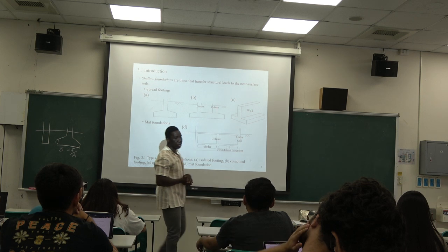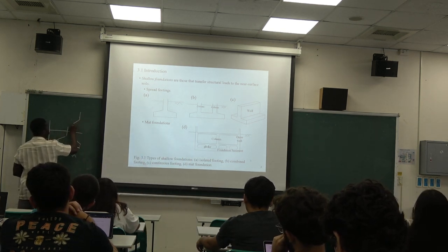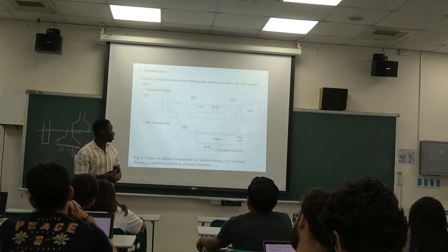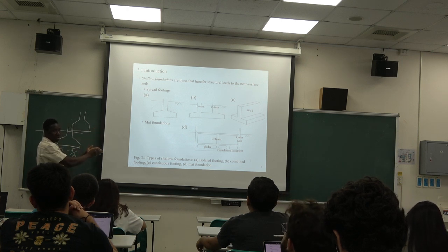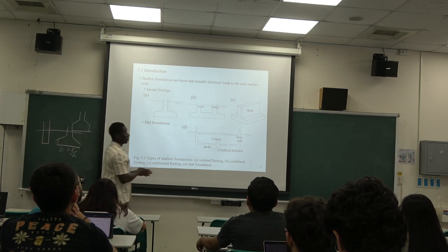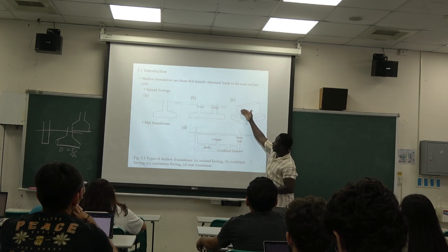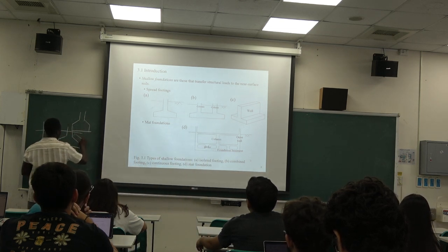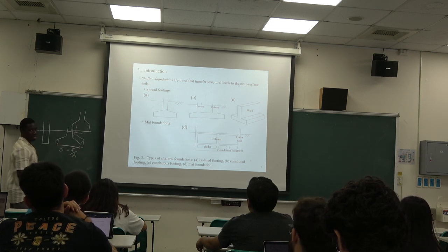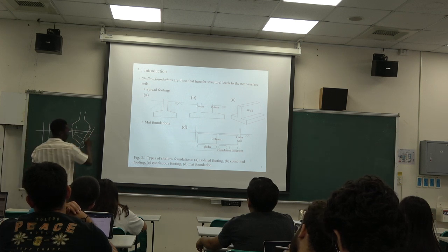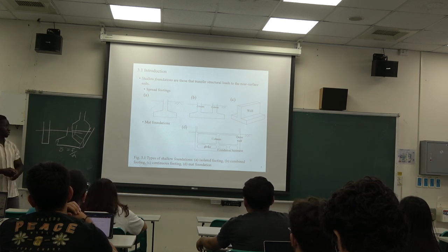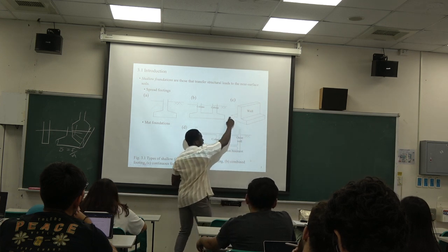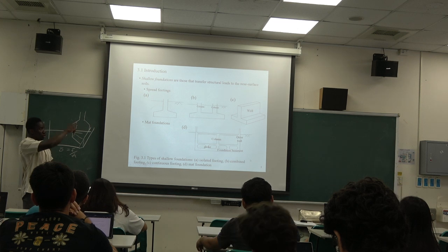And in some cases, you will have a wall. Initially we will design like this: you put one footing here, one here, or maybe you put two together. But if you still feel like this design is not enough, you can just make the footing long enough to go all the way around the building. So instead of having only a footing this way, it goes in. This is a 3D representation. For this one, maybe it's only this big, but in this case the footing is very, very long. This is called the continuous footing, because the length of the footing is much longer than the width.